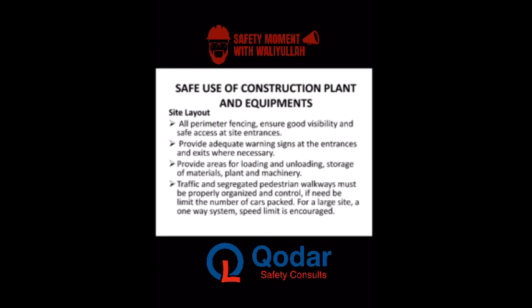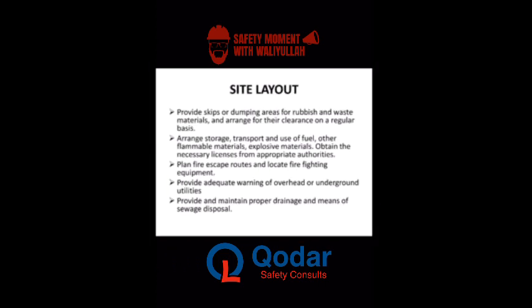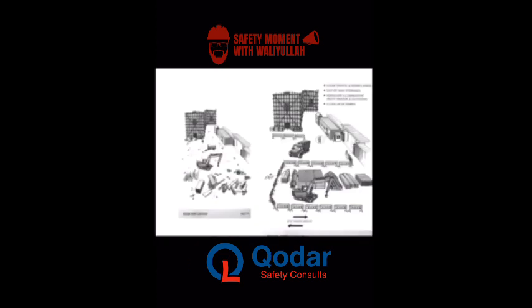Sound and clear, sir. In site layout, first of all, when mobilizing to a site, our site needs to be properly defined. That goes a long way to tell us about our site layouts, our perimeter fencing, good visibility, egress and access, warning signs, loading bay, and storage material. These are all necessary items that need to be prepared before mobilizing to sites. Traffic and pedestrian walkways should be clearly defined. Adequate warning of overhead and utility lines, drainage, escape routes and fire extinguishers. This makes up a very good layout.